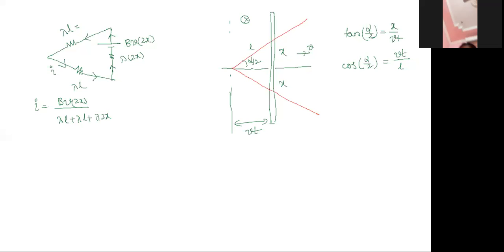Suppose we have an inductor there, and the current I is increasing. What is the duty of the inductor now? It opposes the current. The inductor induces some EMF. Its magnitude is mod E, that is L dI by dt, and its direction always opposes the cause. What is the cause here? Increasing current. So the induced current has to oppose the cause, and since the current is increasing, it should decrease.